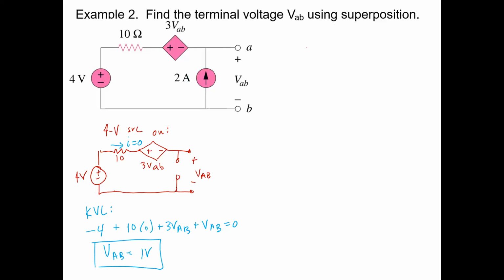Is it easier to solve that subcircuit than the one above? Yes, it's simpler to have only one source in there. So superposition allows us to break the circuit down into smaller chunks that might be easier to solve independently than to do the whole thing together. Isaac. Would we be done? No, we're not done yet, right? Because we have to do the other one. What's the other subcircuit? What do we have to do?